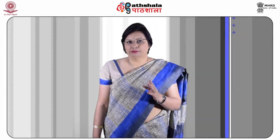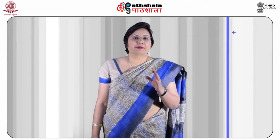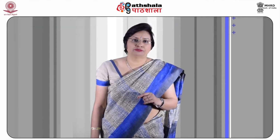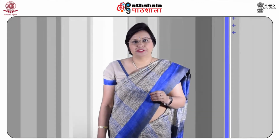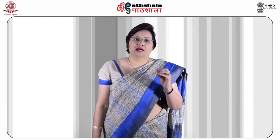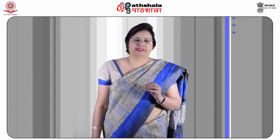Because of the logarithmic scale, a change of 1 pH unit represents a 10-fold change in the hydrogen ion concentration, and this is quite a large amount. Most aquatic animals have pH preferences from 6 to 9. So, if it is less than 6 or greater than 9, it will be a dangerous zone for them. This range is usually maintained by the carbonate and bicarbonate buffering of naturally acidic precipitation.